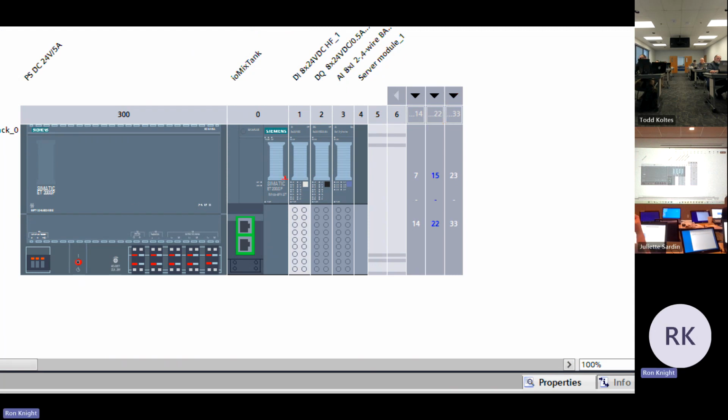Oh, I should mention too, this is the Profinet communication adapter. There you could put an Ethernet IP adapter. So if you wanted to control this IO with a Rockwell PLC, you could. You could put a Modbus TCP adapter there if you wanted to control this IO via Modbus. I don't know why you'd want to do that, but you can, because Modbus just won't die.